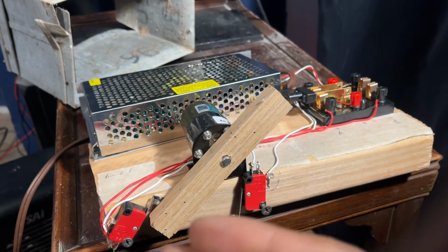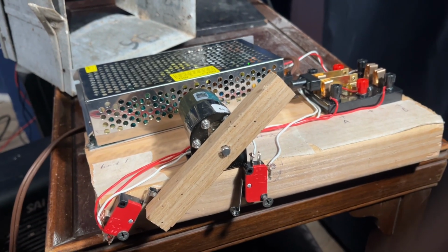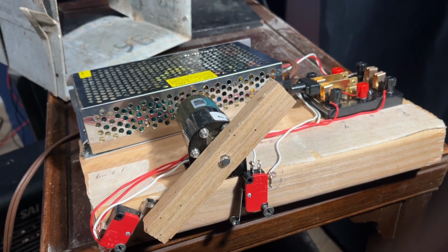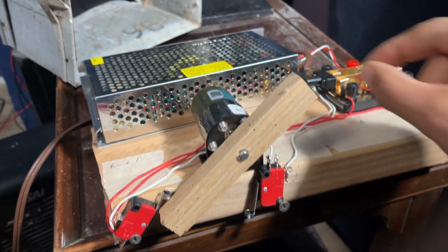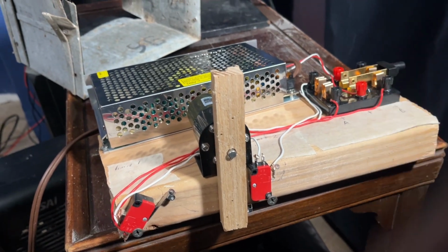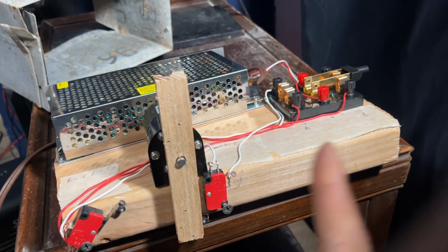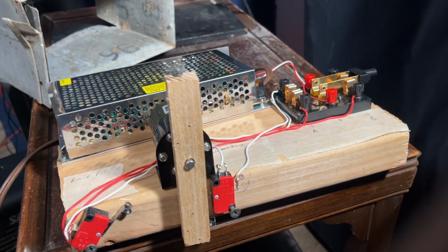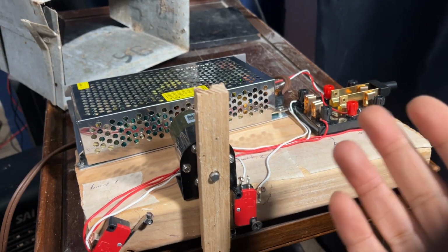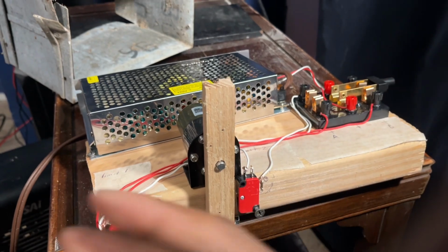Okay, but imagine this is the open position. Air would flow through all of the ducts. Okay, it would heat the entire house, and the thermostat downstairs would be in operation. But once you throw this switch, that door inside of the duct will close, only allowing air to go to the bedroom, which is where I want it. Okay, in the bedroom there'd be an additional thermostat, so while one thermostat is engaged, the other one is disengaged.